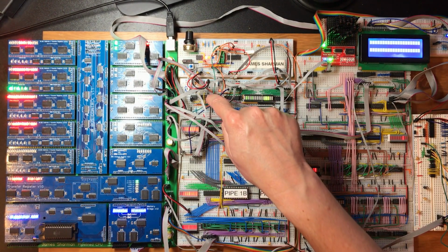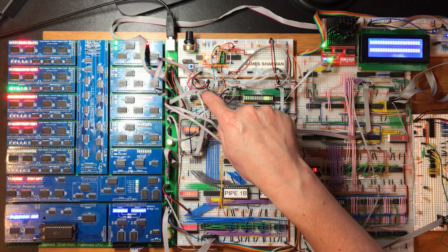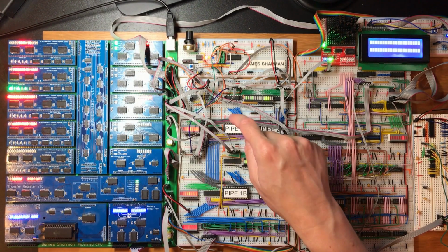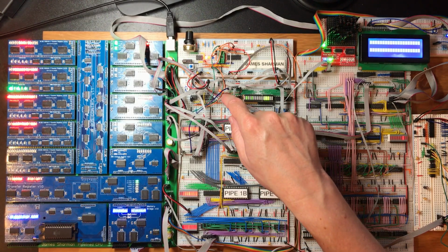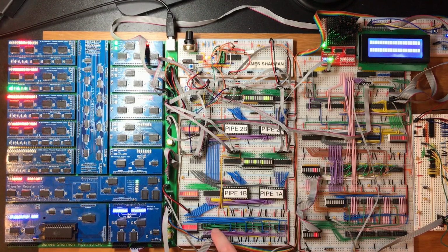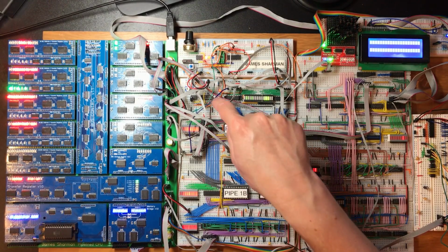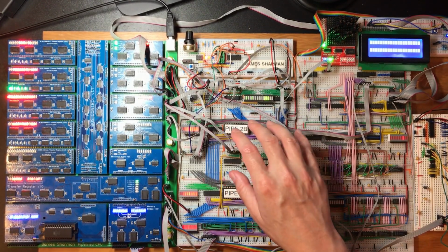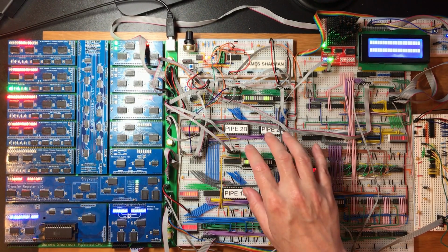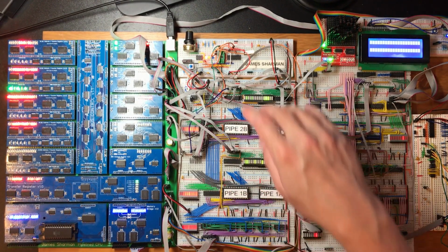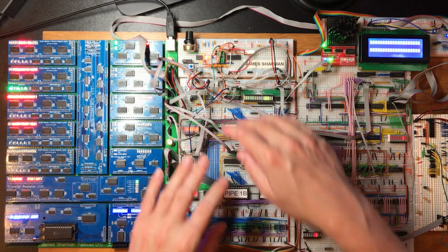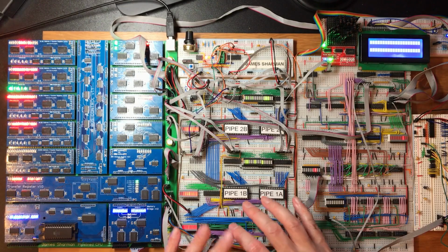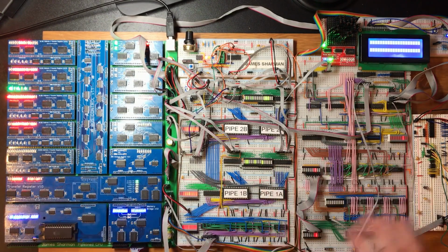In the corner of this PCB, I've got the original reset circuit that mostly just clocks the pipeline several times during the reset and forces the fetch unit to output NOPs, and so that just flushes out all the contents of the pipeline. Now we worked out a slightly different way of doing that with the new clock and reset circuit, but if I convert all of this to PCBs as is, it kind of relies on adding that functionality. So when it comes to testing out the new PCBs, we'll have to work out how to deal with that. Okay, let's get to it.